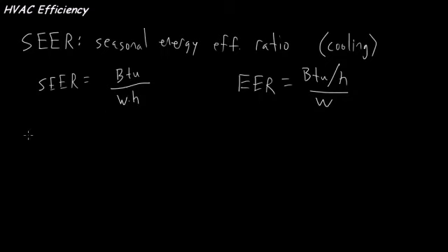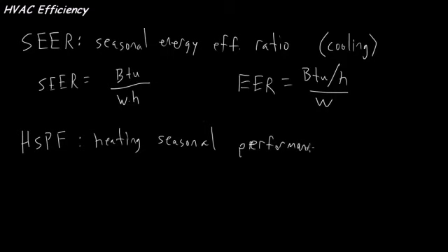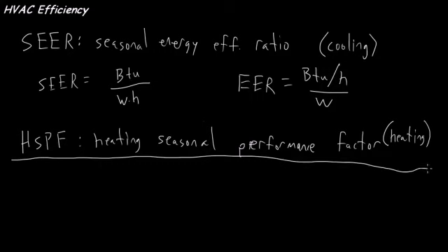We can do the exact same thing with the heating side, except we call it something different. We call it HSPF, which is the heating season performance factor. HSPF is just like SEER, except it's for heating. Okay, so that's heat pumps. Basically, anything with a refrigeration cycle works like that.